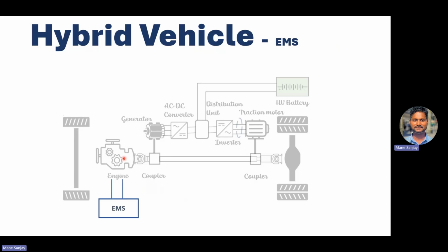It controls the running of the engine by monitoring the engine speed, load, and temperature. It also provides the ignition spark at the right time for the prevailing conditions and meters the fuel to the engine in the precise amount required. All the operations related to the engine are controlled by the engine management system. This engine management system ECU plays a very important role when it comes to management of energy in the hybrid vehicle. This EMS communicates with the other ECUs over CAN.